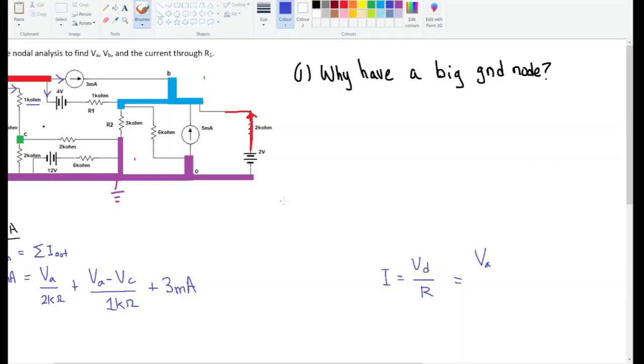So let's say you're at this position here, A, and that's 10 volts. Then you go through a battery the wrong way, and then you go through a resistor and you head to this position B, which is equal to 1 volt. If the battery's voltage is 4, then you lose 4 volts going across it. So you have 6 volts left over, right? So the voltage here is 6, and the voltage down here is 1, which means that when the current moves through this resistor, it drops 5 volts, right? So now the electron just has 1 volt. It gets to the bottom.